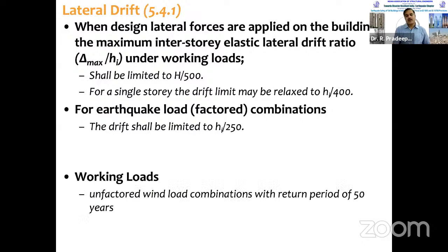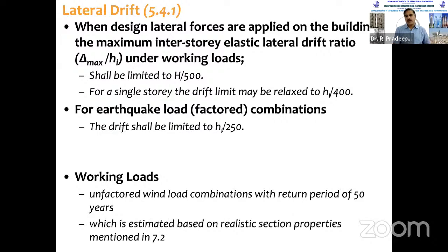So what are working loads? Working loads are unfactored wind loads, and this drift limit is estimated using realistic section properties. That is Table number 6 in IS 16700, the tall building code.